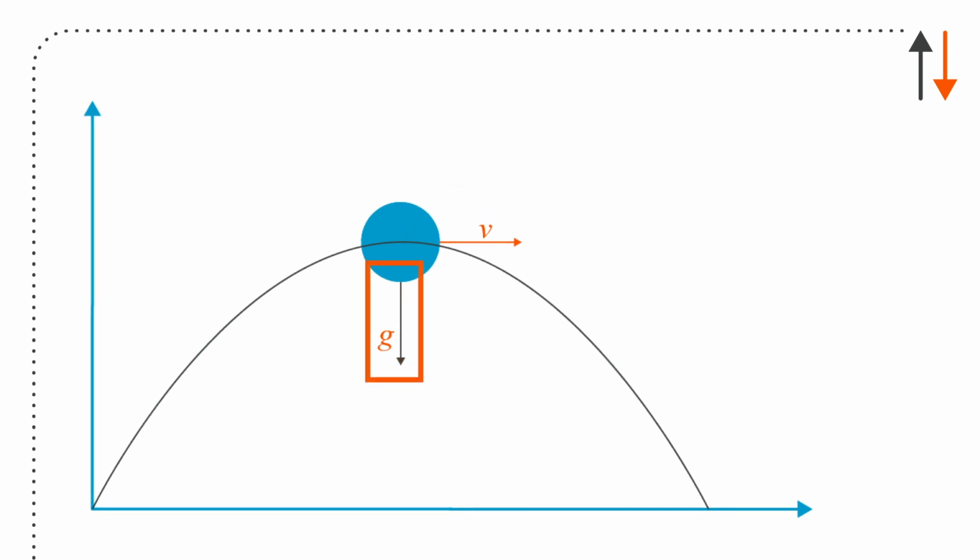Same thing with acceleration. Here, the acceleration is only acting in the downward direction. There's a zero x acceleration. And so Ay and An both are parallel and the same magnitude. And there is no At at this position. If the particle was at another position along the path, then I would have an acceleration tangential in addition to the acceleration normal, and the problem would be a little bit more complex in n-t coordinates. On the other hand, there is an acceleration theta and an acceleration r. And I'd have to consider both of those as I was going through this problem.